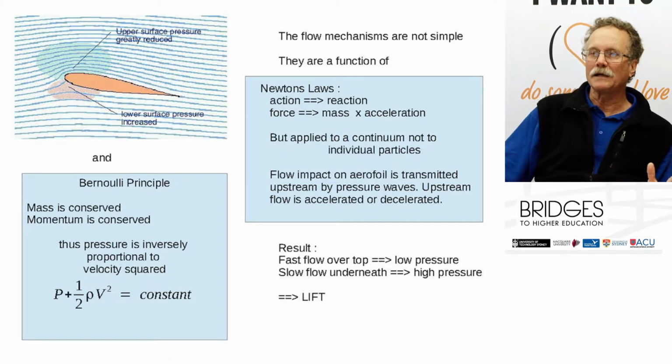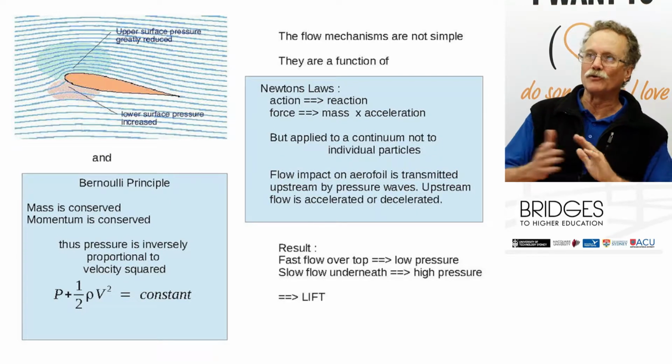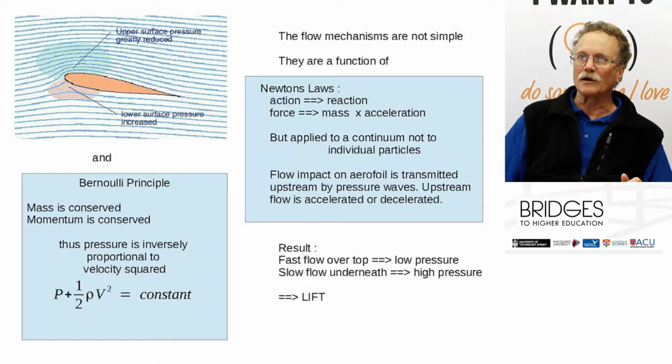Okay, what are the mechanisms involved to make those flow patterns happen? Two things, Newton's laws and Bernoulli's principle. Not one or the other, but both at the same time. So Newton's laws require that for every action there's a reaction, and that can be written briefly as forces producing accelerations for given masses. Now, we're not applying this to individual particles, we're applying it to a continuous fluid. So it's a little bit different than simple particle mechanics, but the effect is that the impact at the front of this aerofoil is transmitted upstream and it accelerates the flow particles around.